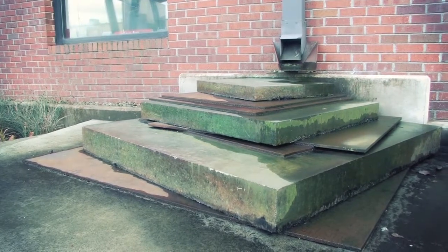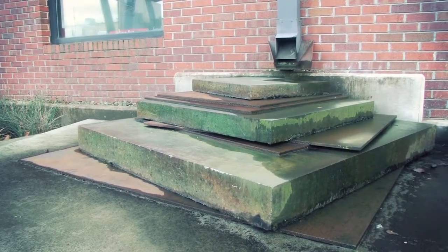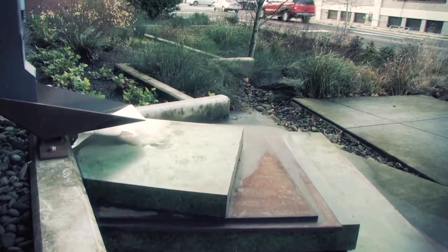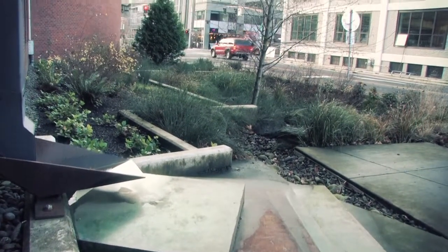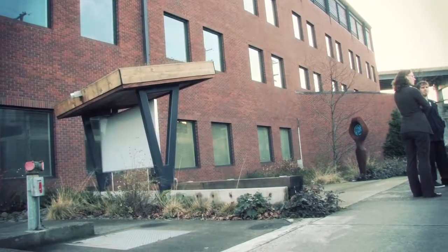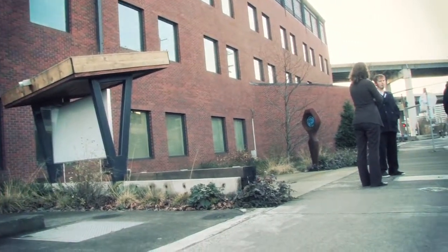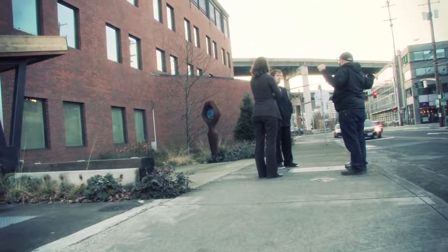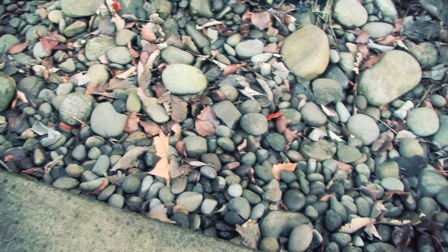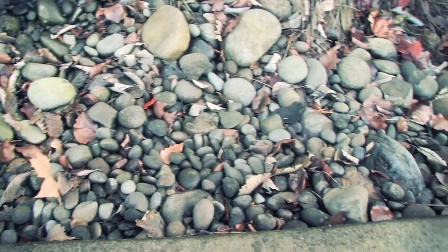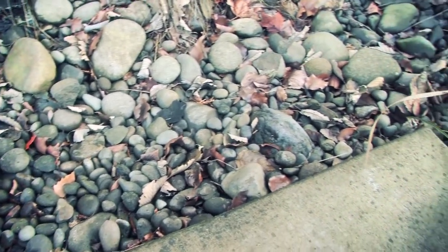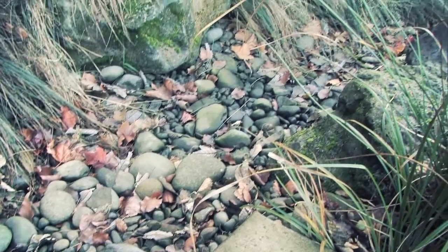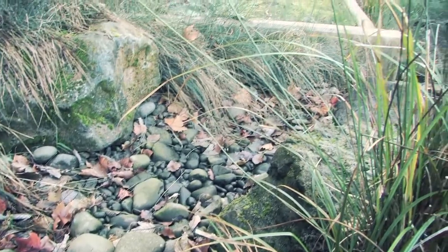Stormwater runoff from the Climb Center's 5,200 square foot roof cascades over a concrete and steel slab waterfall into a rain garden. Runoff from 3,000 square feet of the adjacent street enters the rain garden after flowing under a steel grate that crosses the sidewalk. Stormwater that enters the rain garden soaks into the ground. In a very large rainstorm, excess water flows back into a catch basin in the street.